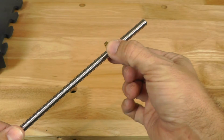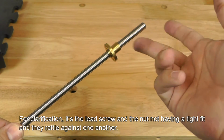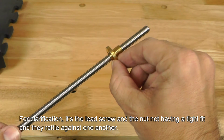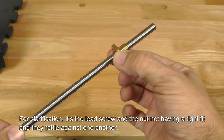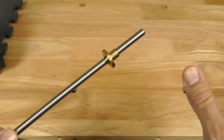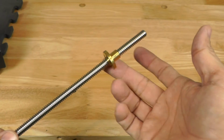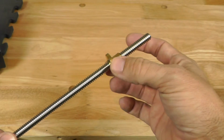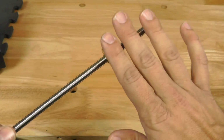That is that lead screw vibrating. And it will create inaccuracies in your print, particularly if you use Z-hop. And more annoyingly for me, it also creates a rattling sometimes that you will hear in your printer. Now, how do we fix this?